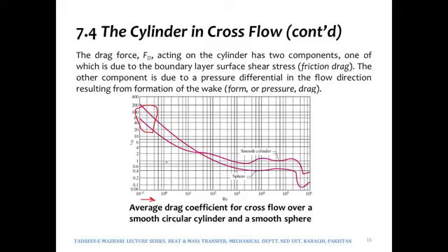Now in this particular region where it is beyond 1 and it is around 10 or so, where the Reynolds number is 10, the separation would start occurring. Separation would then start occurring on the other half, the downstream half, or the rear side, right? So this is what will happen.